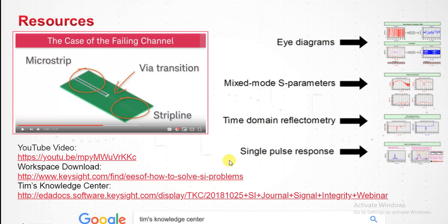Can CTLE overcome discontinuities from vias? Another good question. The reason why I picked DFE is that CTLE is a frequency domain approach, and it really relies on the loss instead of a certain valley, a certain dip of S21. The dip is not happening across all frequencies. Instead, it's happening at a very specific frequency where the stub is resonating. I thought DFE would be a good way to educate people on using a single pulse response as well. Thank you.